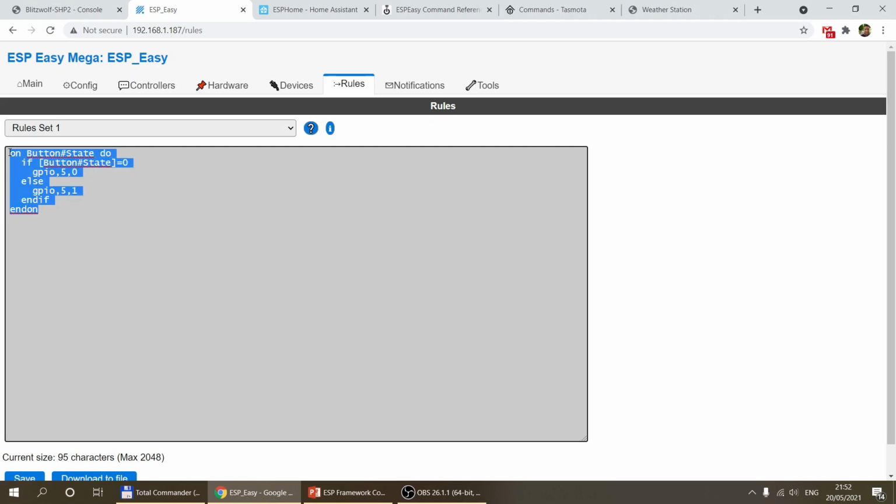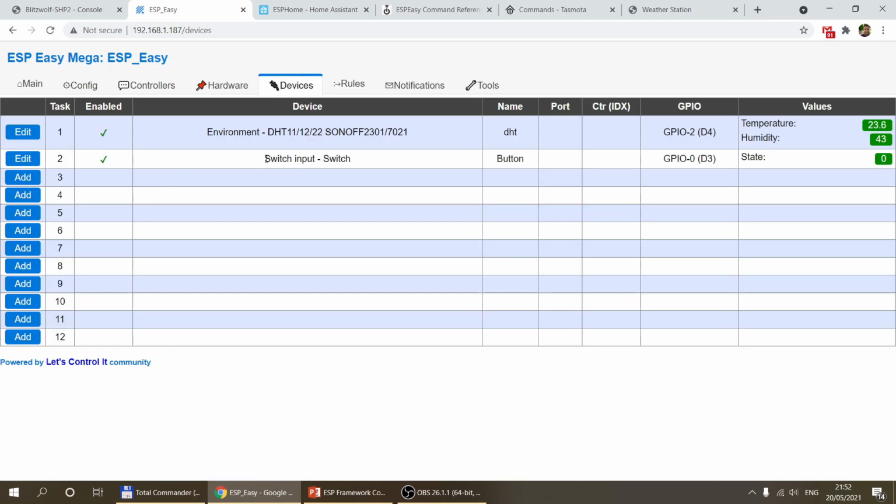I mean, if I don't create this rule, then what I could do is program the input switch as a device, which then sends a message, for example an MQTT message that I pick up in Node-RED, and I send the signal to turn on the relay, which is absolutely fine. But again, let's say if my Node-RED is down, that button is not going to do anything.